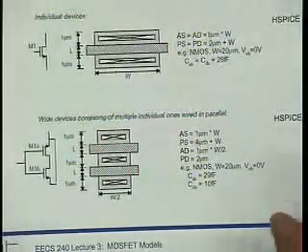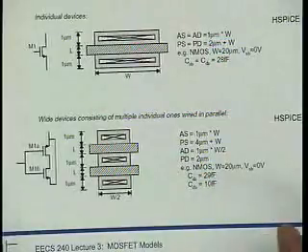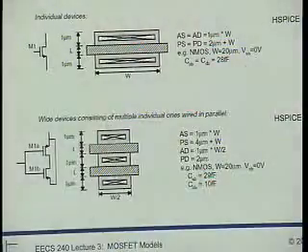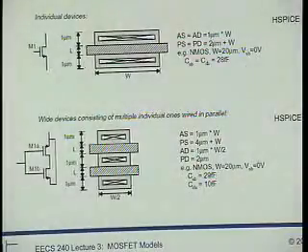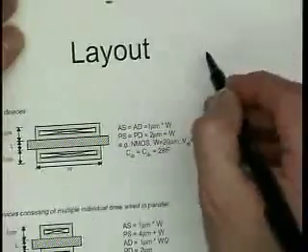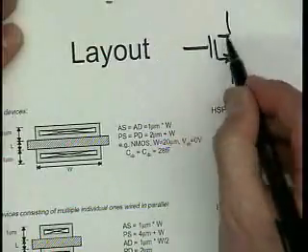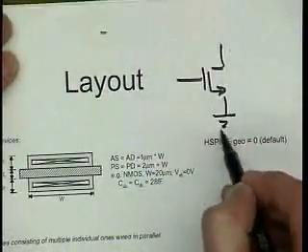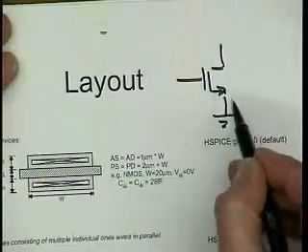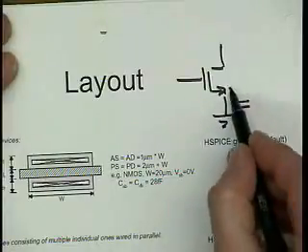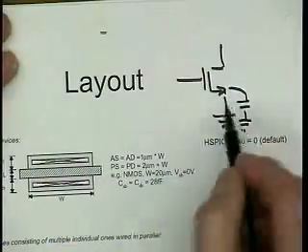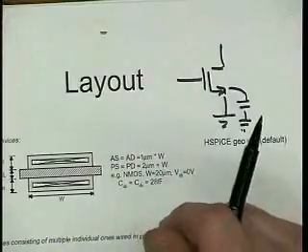In particular, the source to bulk and drain to bulk capacitance, we have some handle over, and an example is shown here. Suppose that we want to build a common source stage. Then the CSB is just in parallel, it's just shorted out, right?